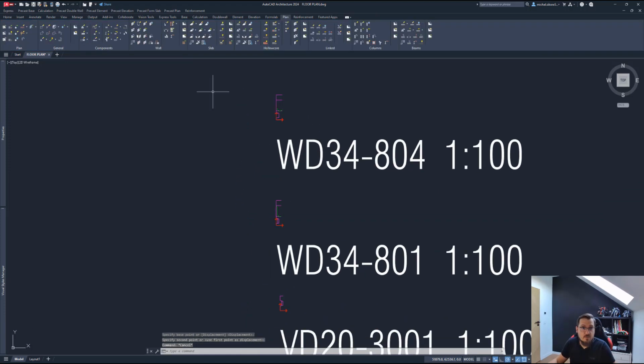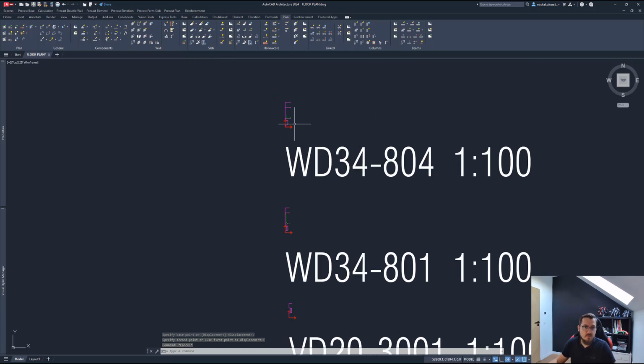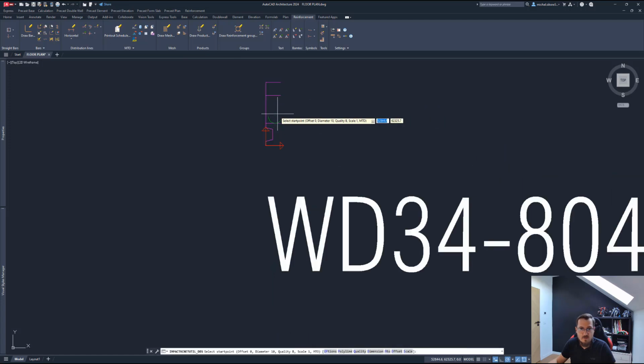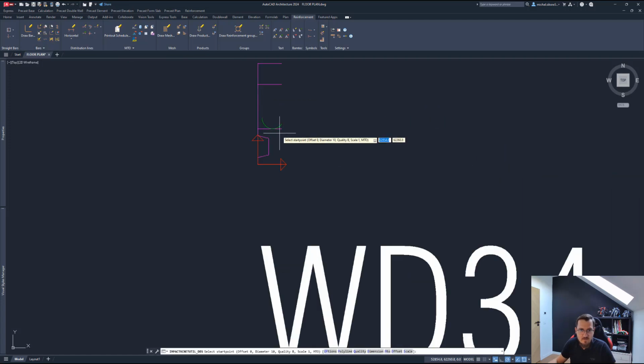Okay. All right, so now in order to get the reinforcement in, I need to go to the reinforcement tab, and I actually need to create a bar, and that's from the bars tab. What I want to do is specify the dimension of that bar. I can make that a size 10. I also want to apply offsets. Offsets will be my covers, and I'll make that 25 millimeters. Accept that. Or maybe let's make that 20. I think 20 was set for the wall reinforcement. So my offset is like that.